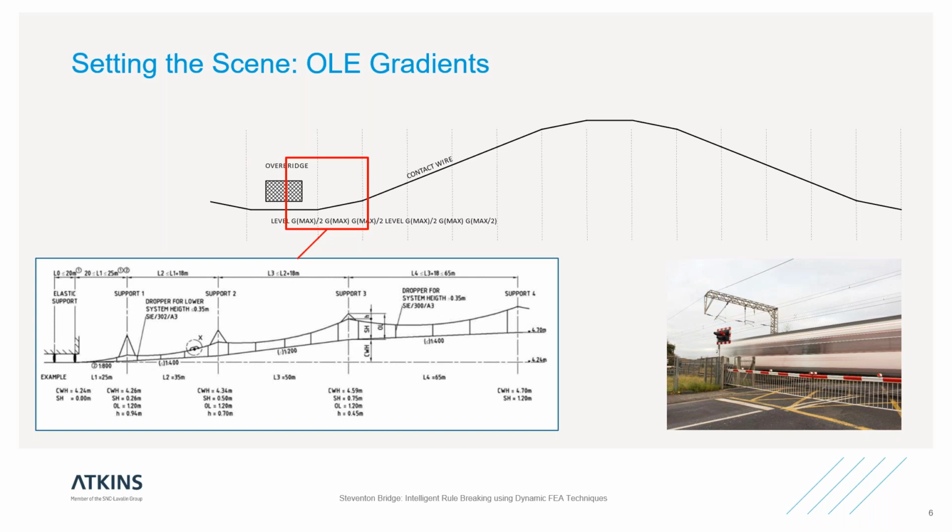Meanwhile, at level crossings, we have statutory minimum wire heights to meet in order to deliver electrical safety for road vehicle drivers. There is no maximum legal limit on a road vehicle in the UK. I bet you didn't know that. But most road vehicles are up to, but no higher than 5 meters. So that drives our level crossing wire height design.